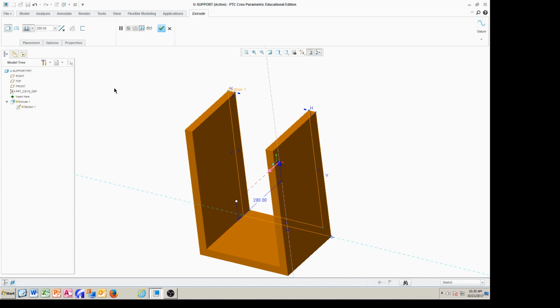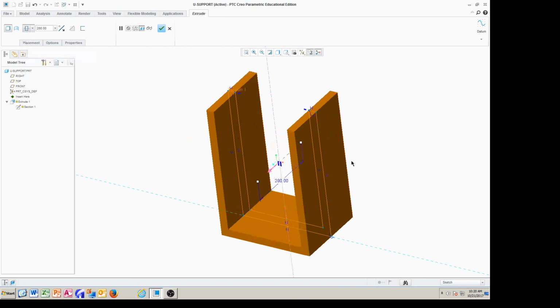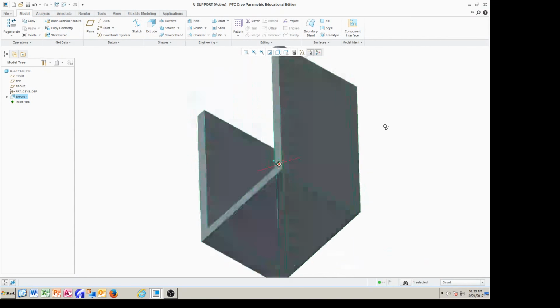Okay, I'm going to extrude that. This will be a good habit, to extrude in both sides. Extruding in both sides will be great, because in case we need a mid plane, by doing that you're going to have a mid plane. So we say we're happy with that.